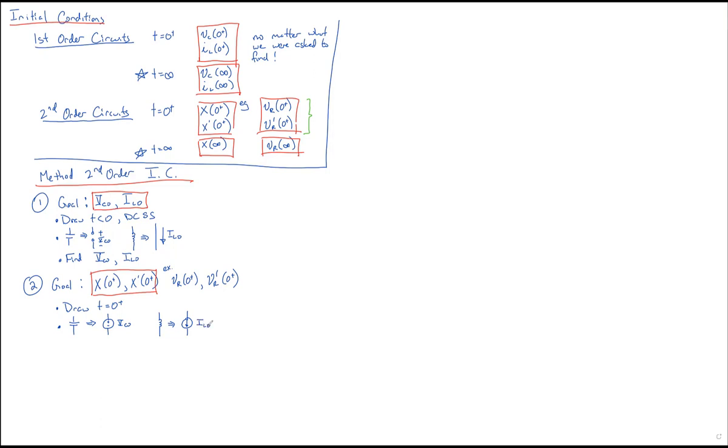And it's important to use passive sign convention if you define any extra things around it. So for instance, if we're defining the current going down, then you have to define using passive sign convention the voltage across that inductor like this. Because again, it's not really a current source, it's really an inductor.